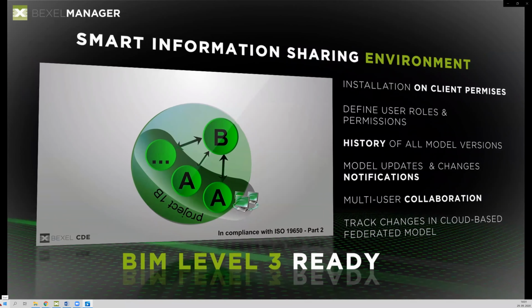And we talked about this topic, how to import a BXF file, in lesson 4. And I have imported it because I will use certain groups of those elements within the custom breakdown to create selection sets. So if I previously select elements and create a regular selection set, then this selection set will not include new elements which would be added during the process of an update of the model.